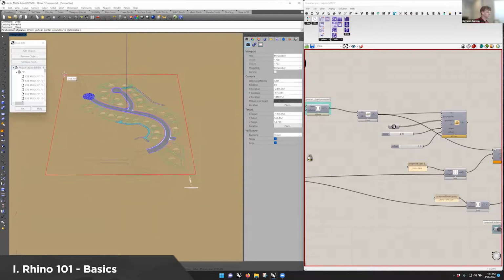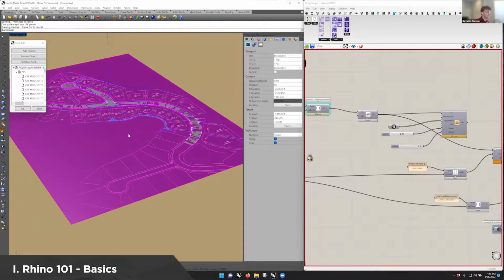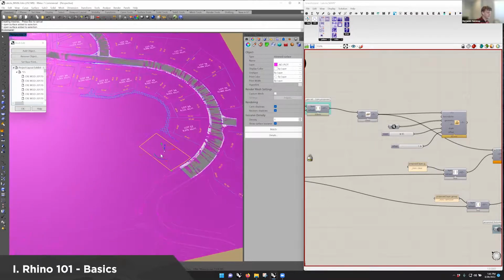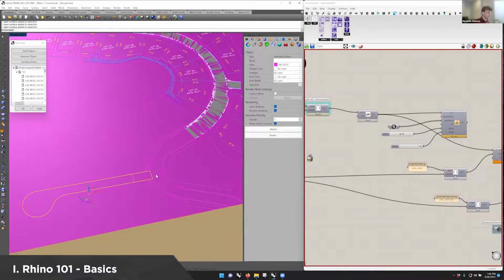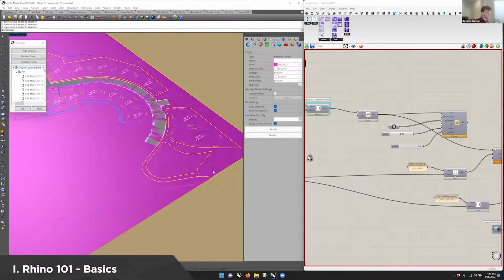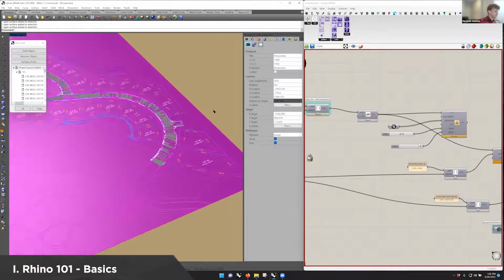So I could just create a surface across this entire area, then hit split, grab all of these objects, and see what gets split and what doesn't. Here you can see that it's splitting all these little pieces, so those are all touching each other appropriately. This one actually ends up being a pretty good survey to work with. But yeah, it's a good thing to double check,